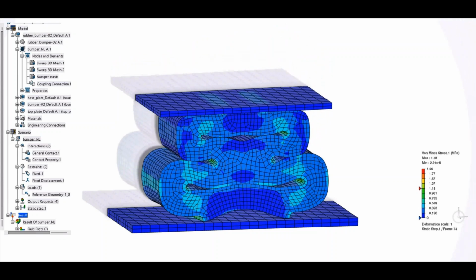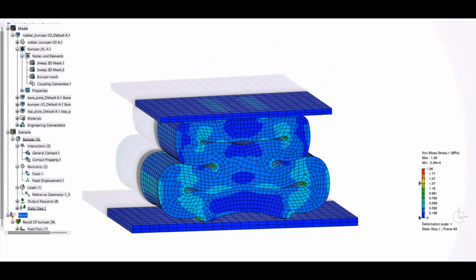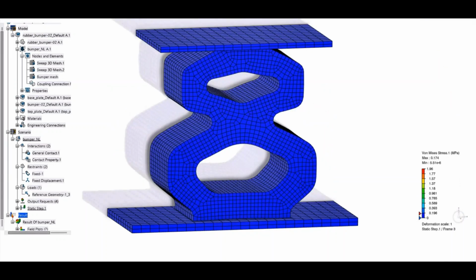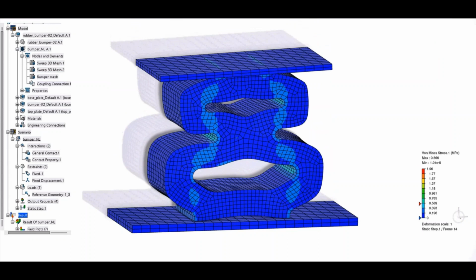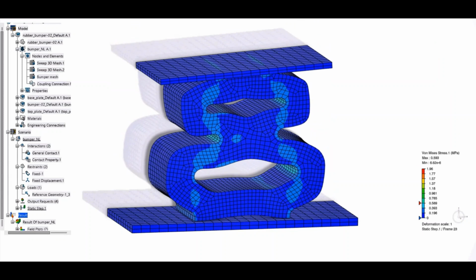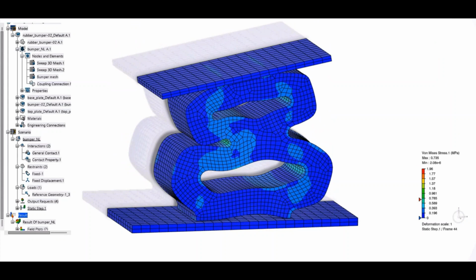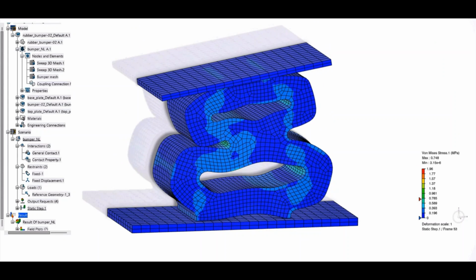And then you can see again here the flat part on the bottom is leveraging, is going up. So it's a much more complex situation. And for example, here I have used the Ogden model, which is much more robust than the Mooney-Rivlin.